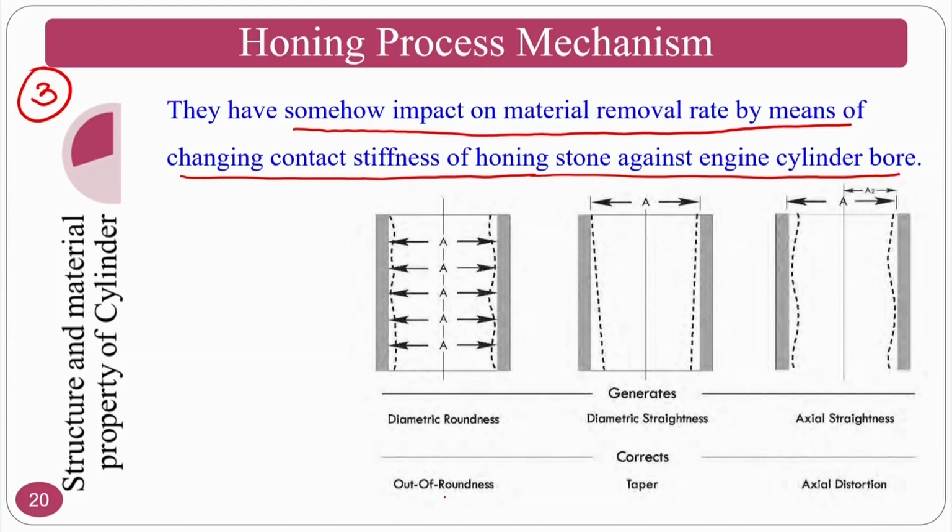If the shape is like this, whenever my hone sticks are touching here, the pressure will be different. Touching here, the pressure will be different. Okay. So, you should be careful about the shape, size and other things of the workpiece.